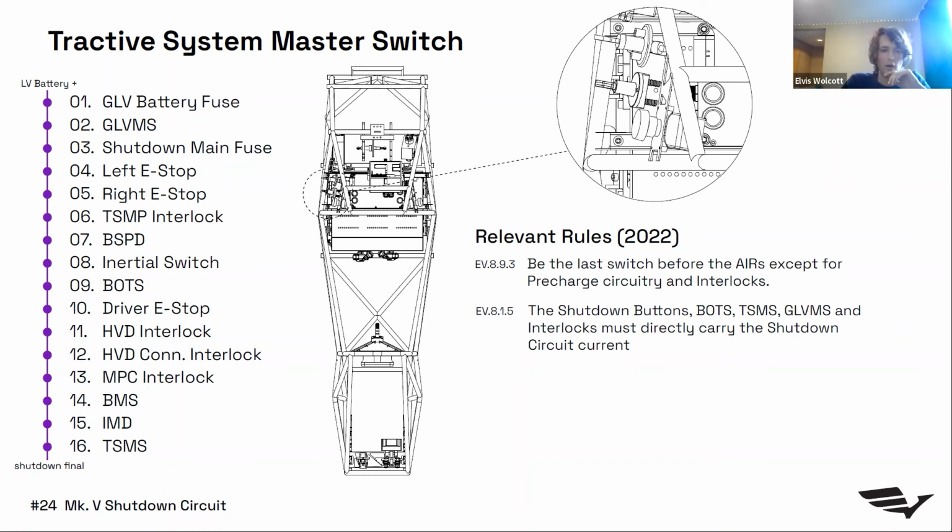I think that in Mark 4 tech inspection, I believe I was told that it got hot enough that the pre-charge resistor desoldered itself from the circuit board because the solder just melted. And so it's definitely something to be aware of. We have some thermal numbers for this year, which suggest that every time we do a pre-charge discharge, the temperature of the heatsink increases about 4 degrees, which isn't that bad.